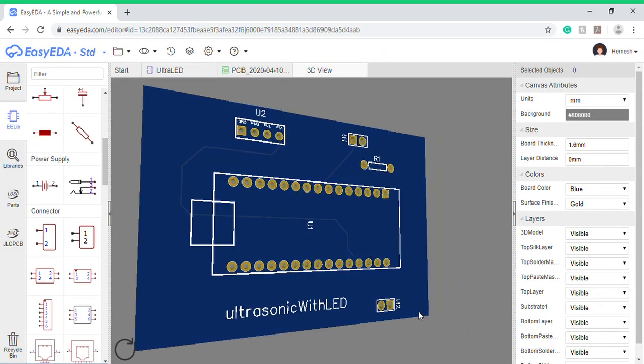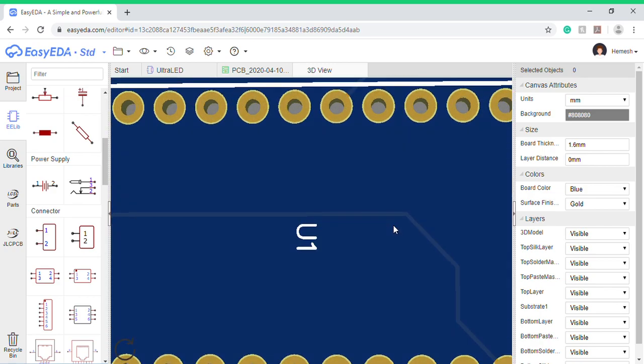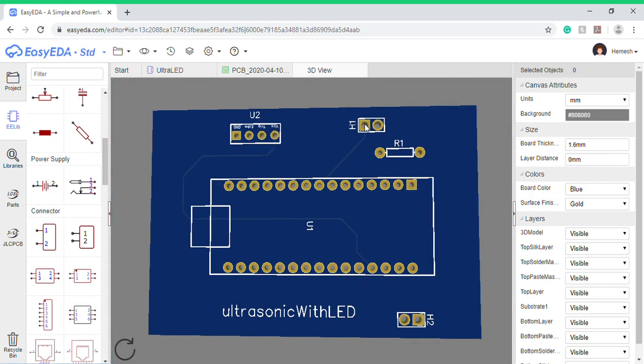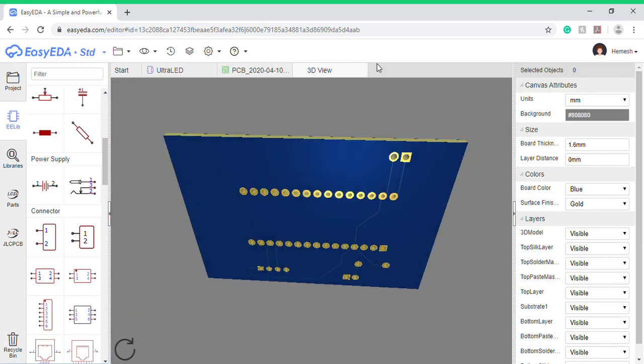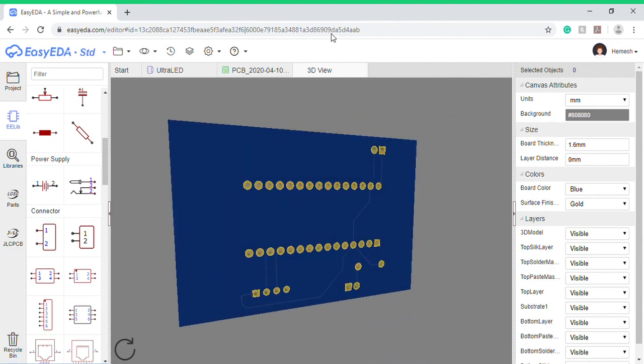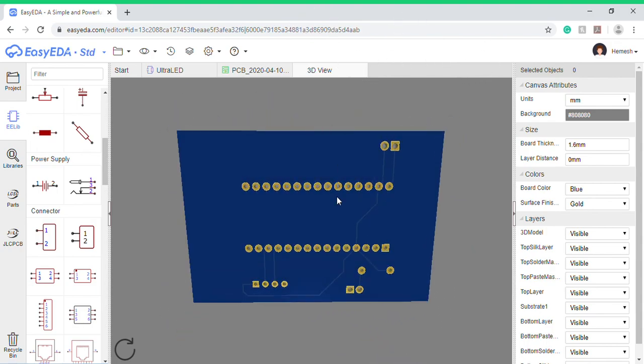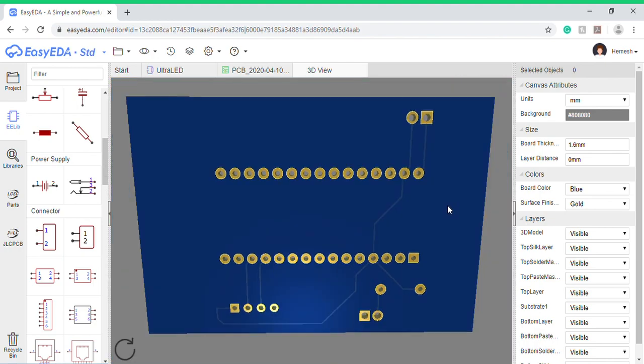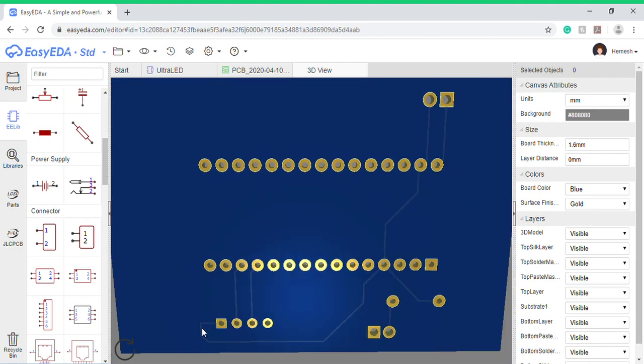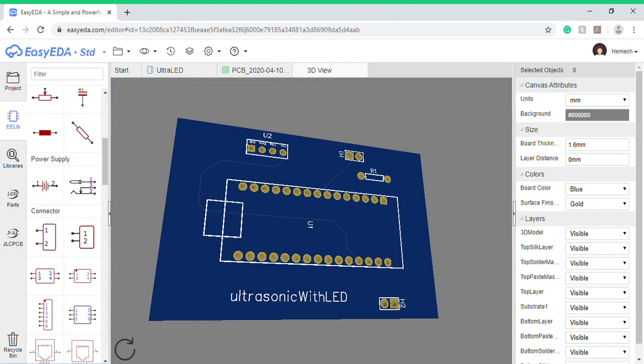As you can see, this is the top layer of all of them. You can see the connections we made on the top layer. If I go to the bottom layer, as you can see, the rest of the connections. This is more easy to understand, I hope. See, this connects here. As you can see, if I go to the other line, these both intersect, but both are in different layers. So that's not a problem.